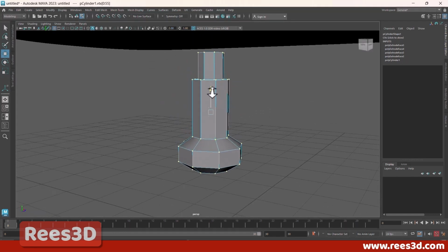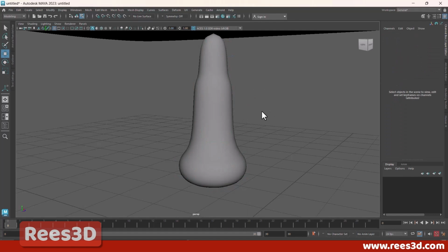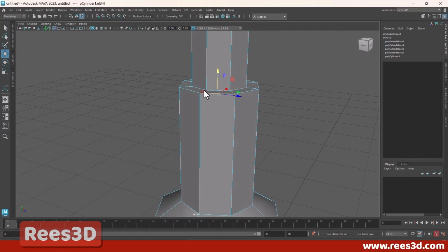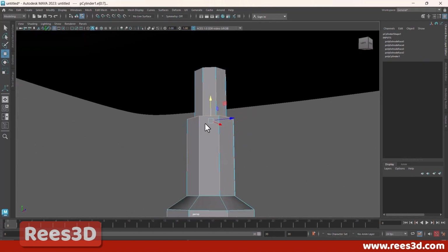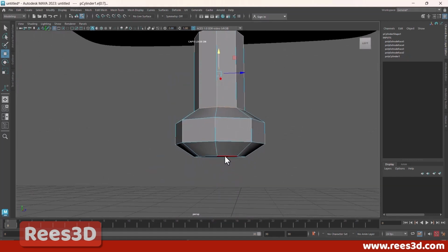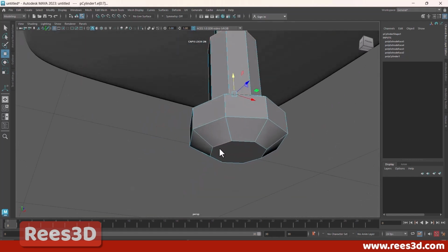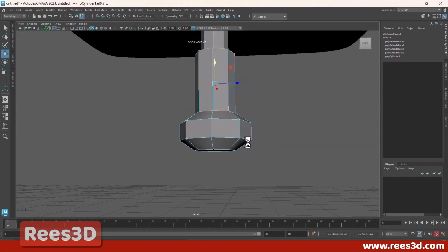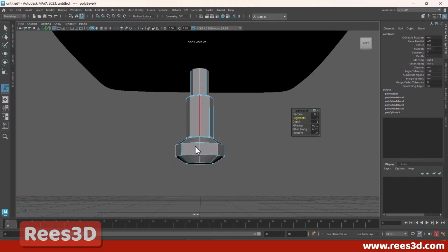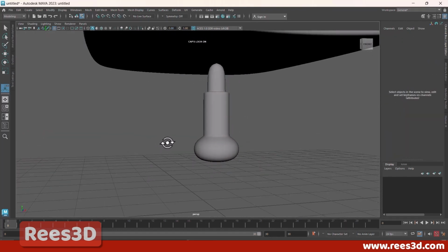All right, so now I also want to add some bevel everywhere, just to make the overall shape look smooth, especially when I press 3. Okay, so let me just go to double click on this guy, double click on this guy, double click on this one. I think these two we can just leave it as it is, and also the bottom we can leave it. So bevel edge here. Let me add segments, maybe just 2 is enough. This time if I press 3, it should look like this, so that's fine.